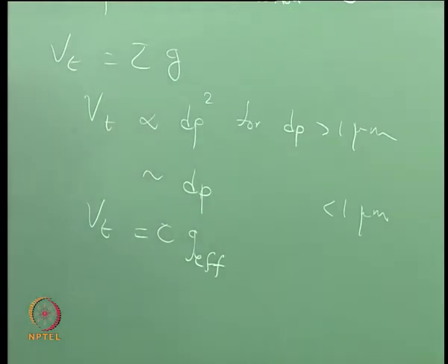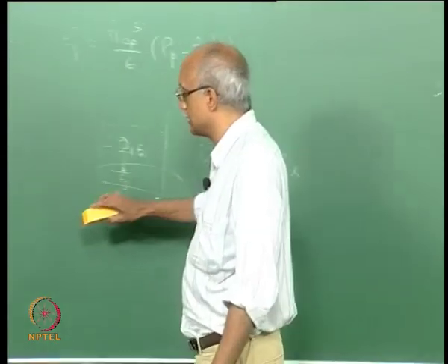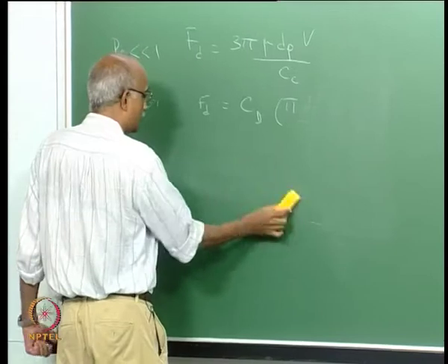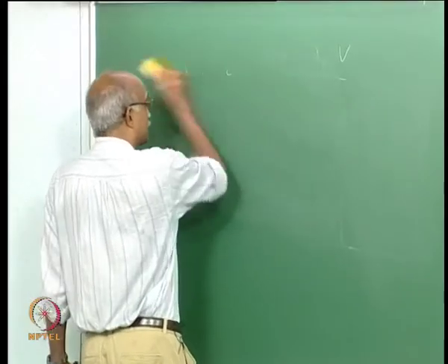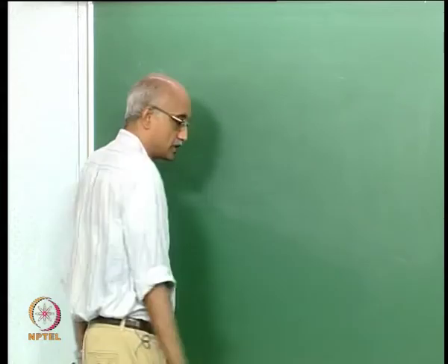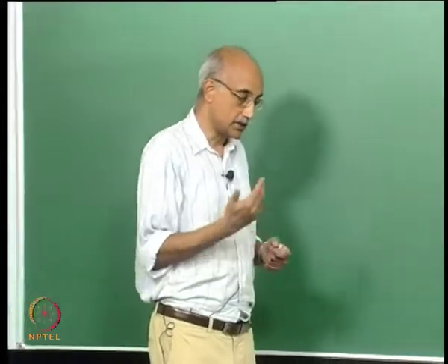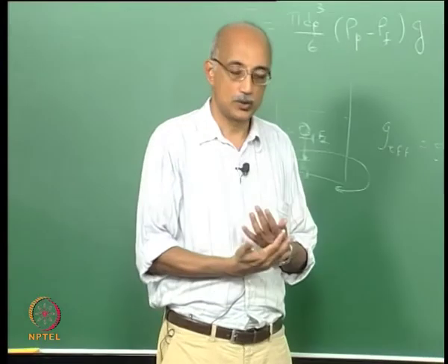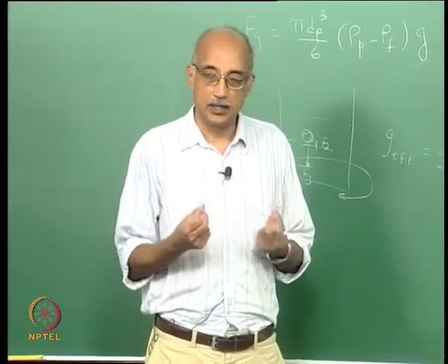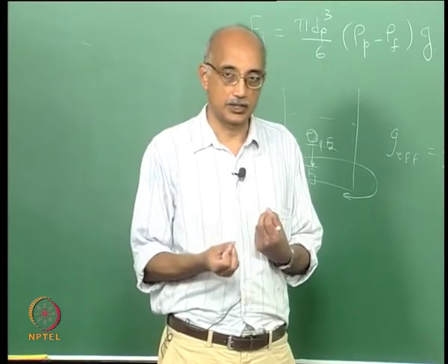Okay, now let us look at how this leads us into our definition of a dimensionless parameter that governs inertial transport of particles. Now, as I mentioned in the last lecture, as particle size changes, so does the predominant force field. So, when particles are very, very fine, diffusion and electrostatic effects dominate.